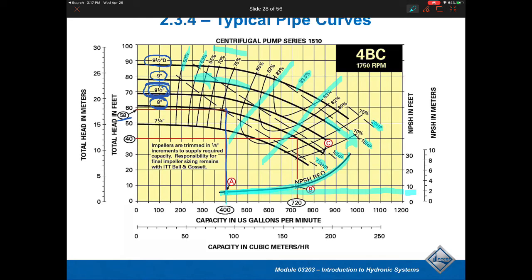Also on this curve, you're going to notice that they give you some horsepower requirements. If you're going to select a pump on a commercial job, the engineer has to select a pump. Well, he's got to know what size motor is going to be needed for that application.